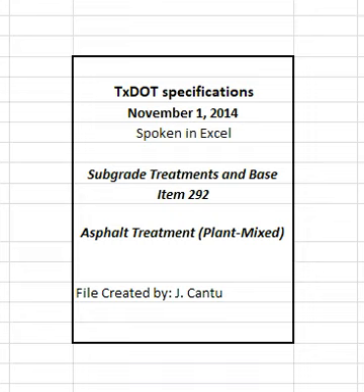Leveling courses and other areas may be spread with a motor grader when shown on the plans or approved. When hot mix is placed in windrows, operate windrow pickup equipment so that substantially all the mixture deposited on the roadbed is picked up and loaded into the spreading and finishing machine. Adjust the hopper flow gates of the spreading and finishing machine to provide an adequate and consistent flow of material.